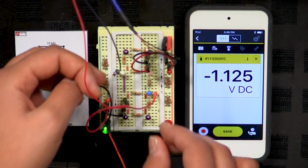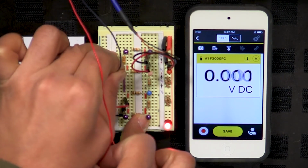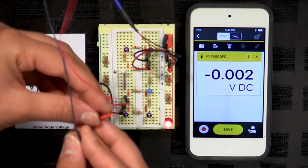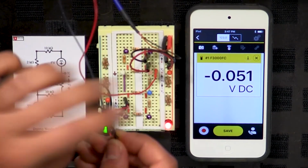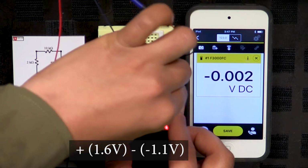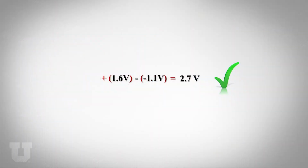So let's measure the voltage drop across V0 and see if the measurement is equal to what we calculated. Again, we put the positive where the pink pin is, V1 with positive minus V2 with negative. 2.7. That is exactly matching what we expected. And the node voltage helped us to find voltage drop.